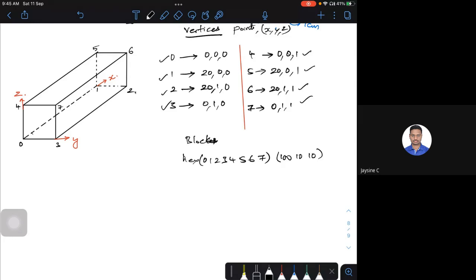Then you have to start with simple. So G should be capital here. So simpleGrading, and then put either 1, 3, 3 or 1, 2, 2 or 1, 1, 1, it doesn't matter. So how are we going to do that? The grading, that division grading will depend upon what you are going to define.